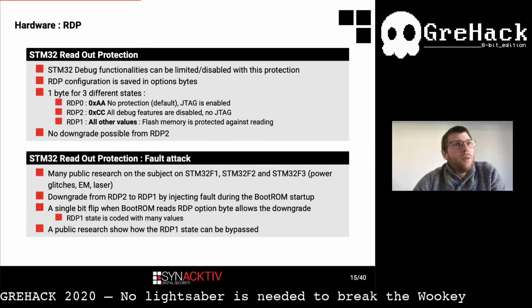First, RDP0 is the state where all debug features are enabled, including JTAG. In this mode, which is the default mode when you receive the MCU, you can debug the code running on it, and read the RAM and the flash memory.